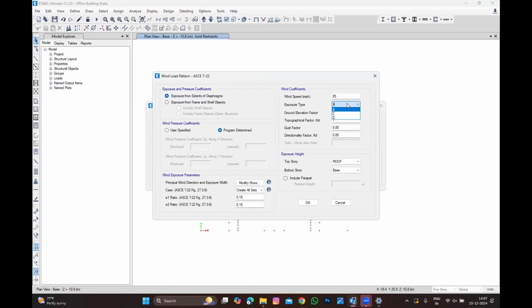The best way I can say it: if there is a road, either 2 lanes or 1 lane, doesn't matter, it is called open. When the building touches with the setback, then it is called closed. It considers less wind compared to this. You don't need to go for D. D is straightforward and very clear: all four sides open. When you make sure it is D, okay, but don't go for a conservative D.